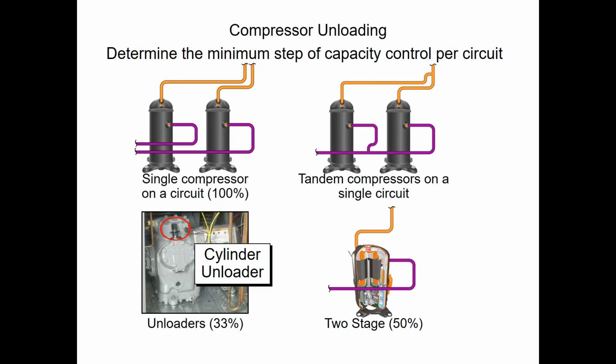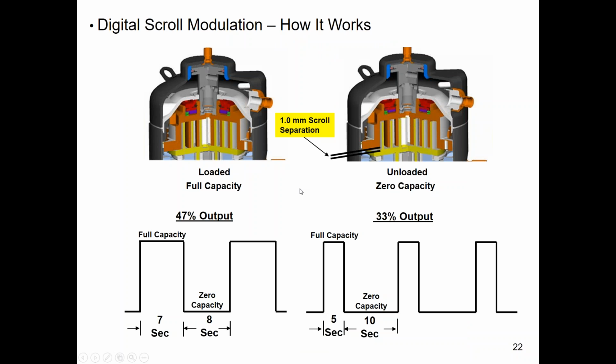Also on compressors, right now we don't have any variable speed compressors on commercial size condensing units. I'm assuming that's true. Not yet. Right. But we have them residential, we have them on chillers, we have them on rooftops in a few weeks here. We don't have them on condensing units at the present time. Digital scroll is the alternative on the condensing unit side for the present time. It won't be long though. If we got rooftops, chillers, and residential with inverters, we're probably going to make an educated guess that the split systems will have them too.